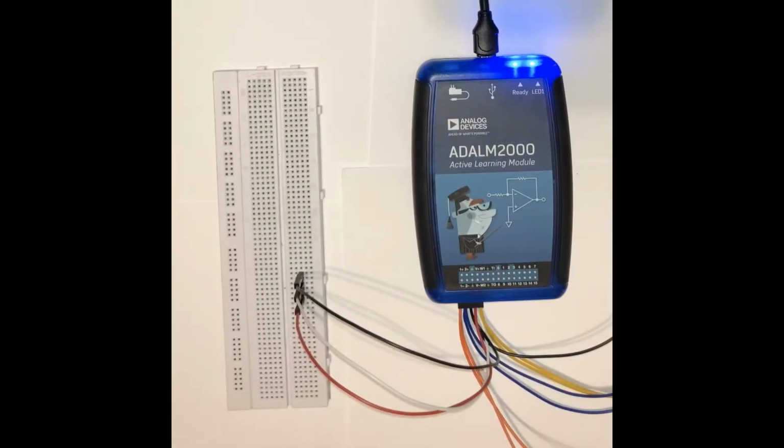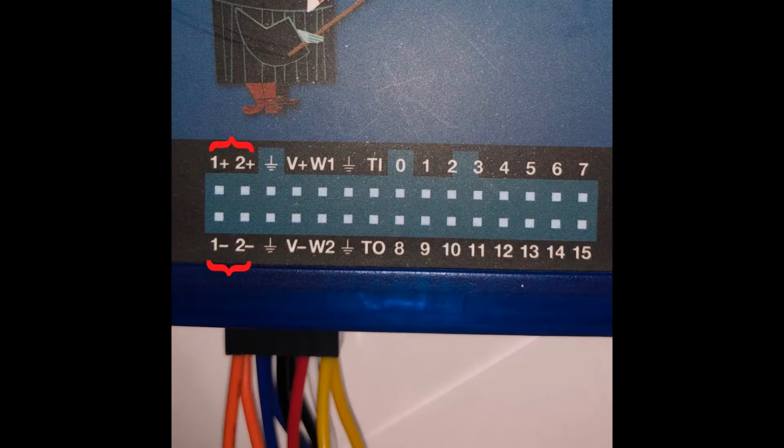As mentioned in the previous video, the voltmeter is a device used to measure voltage in a circuit or across individual components. In order to demonstrate the voltmeter, I will be using the power supply connections from the previous example, including a couple more red and black wires and some of the analog probes from the M2K. I will be using both the orange and blue analog leads, labeled 1+, 1- and 2+, 2- respectively, on the pinout diagram of the M2K.